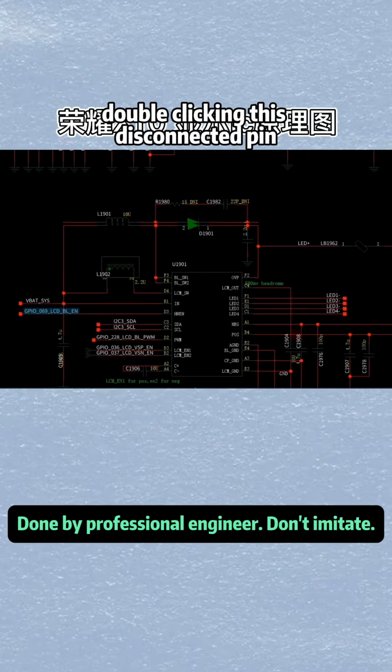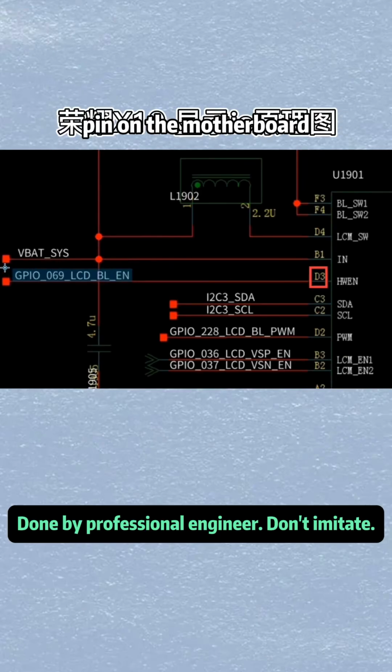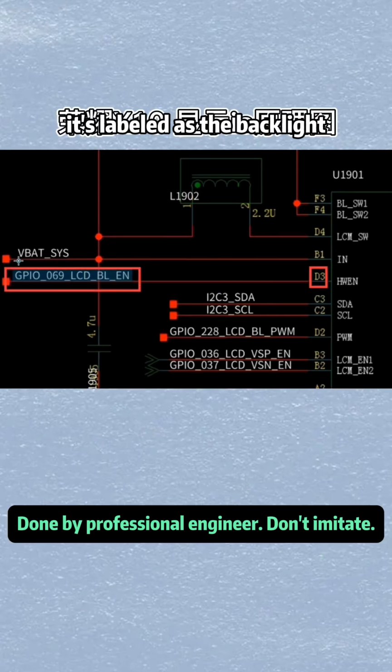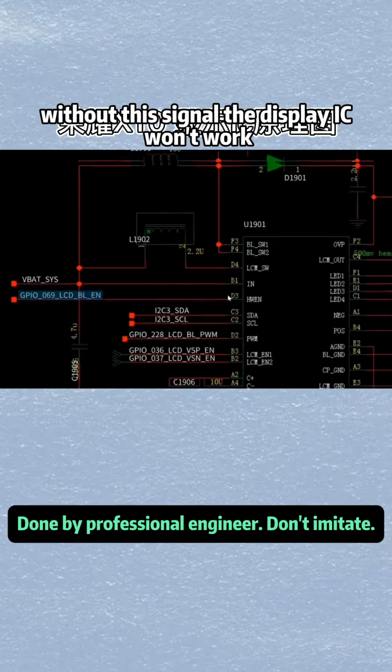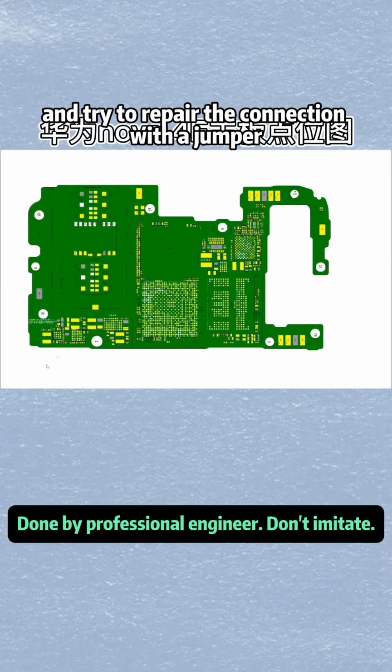Double-clicking this disconnected pin takes us to the schematic. The disconnected pin is the third pin on the motherboard. It's labeled as the backlight enable signal from the CPU. Without this signal, the display IC won't work. It seems we'll have to remove the CPU and try to repair the connection with a jumper.